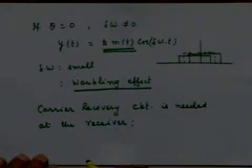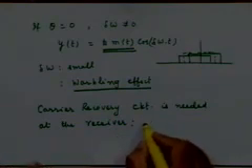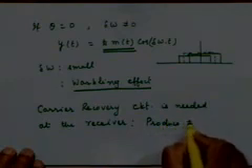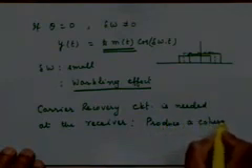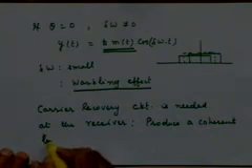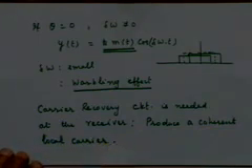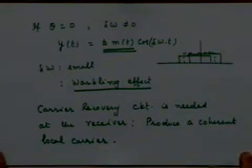And what will the carrier recovery circuit do? So produce a synchronous carrier, produce a coherent local carrier, right? And this kind of a thing can be done by using a device called the phase lock loop, etc., which we shall discuss a little later, right?